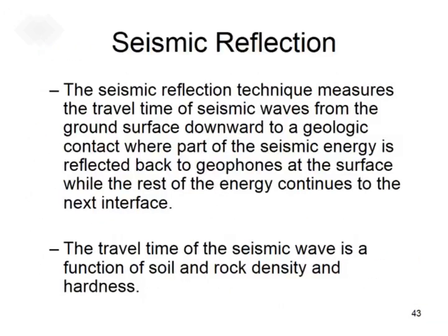For seismic refraction, normally the wave travels along or passes through the material. However, for seismic reflection, the wave reflects from the source to the receiver. Normally seismic reflection is ideal for mapping geology at a certain depth, deeper compared to refraction.